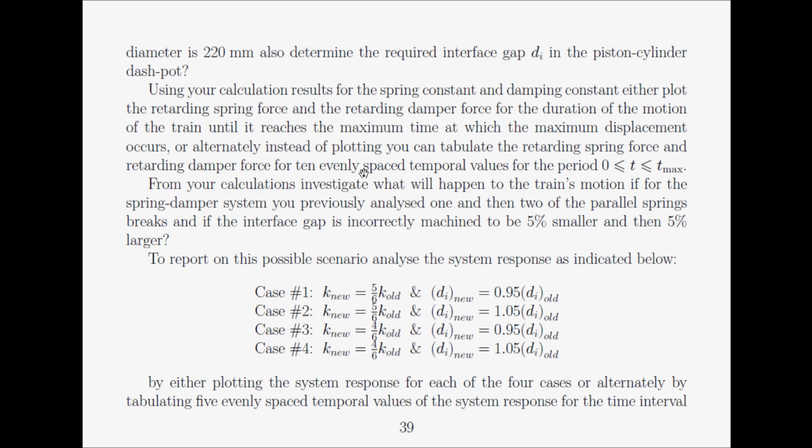This is basically a critical damping system. So the previous problems were underdamped systems, mainly in question 3, where zeta is less than 1, 0.5, 0.93. We worked out a particular value for zeta. In this particular problem, zeta is equal to 1.0. In other words, it's a critically damped system. There are other problems that you'll look at in your textbook for overdamped systems.